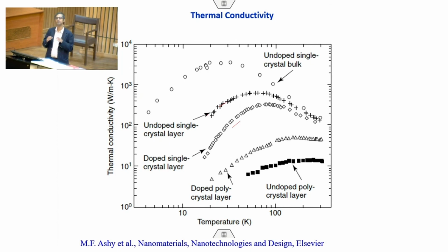So if you want to have a thermal barrier, you can do that. You can create a multi-layer structure, and then within each layer you can have nanocrystalline grains. So substantially, thermal conductivity will go down, and that is what is used. But then the question of the stability of these grain structures comes into the picture. As you increase the temperature of the material, the nanocrystalline grains will grow, and their grain size will become very large, and hence the thermal conductivity will change. So this aspect is important. That's why many scientists do not go to very small grain sizes in each layer, but they reduce the thickness of each layer substantially, and each layer acts as a separate layer, so they don't interact much. So that's something which is very important.